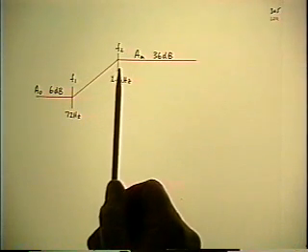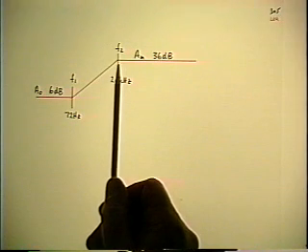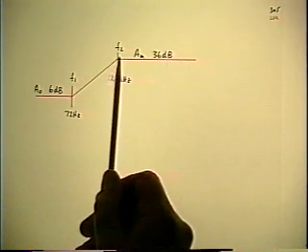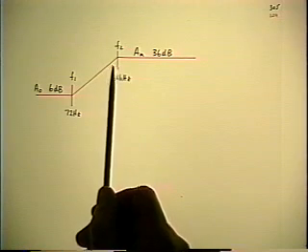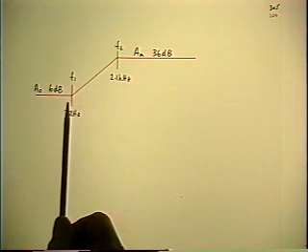You also have to meet the specification for this corner frequency, because you have to maintain this gain down to some specified value, and there probably isn't even a spec at all on the other one.